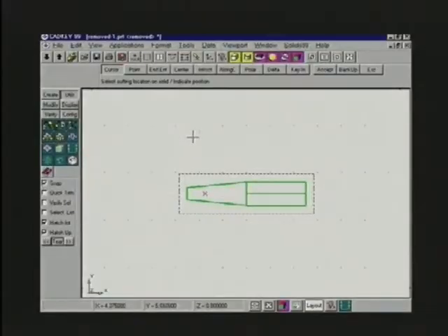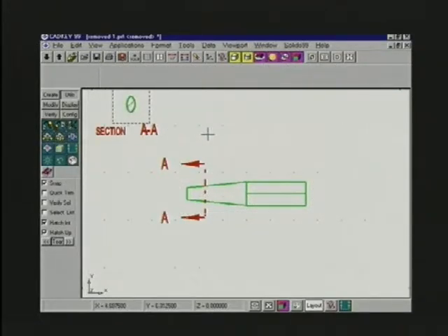And the first cutting location is going to be here, and I'll make the arrows point to the left. And then I'll take this section, and instead of putting it right in place and revolving it in place or putting it off as a right side section view, I'm going to remove this and place it up here out of the way. And then I'm going to cut another one, because you see the shape there now. I think you can see that on the TV screen.